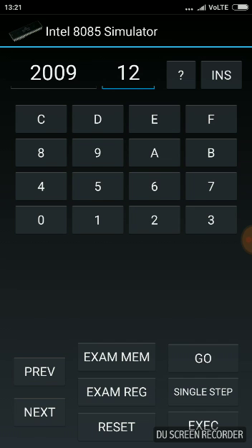Right, now we store from the accumulator into the memory pointed to by the register pair. The instruction is STAX D, which stores from the accumulator into the memory location contained in the DE register pair. The opcode is 12. Right, now we have stored our data from the HL register pair location into the DE register pair location. We have to do this 16 times.